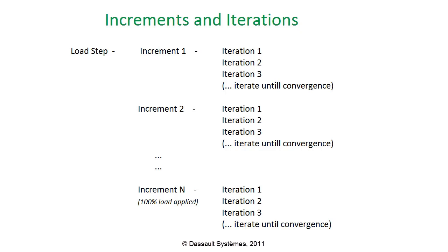It is hard to determine exactly what will be a good initial increment, and Abaqus will in fact let you change even more options, such as limiting the minimum and maximum increment sizes, as well as the total number of increments. However, an initial increment of 10% is generally assumed to be a good starting point, unless you have already run the simulation previously and examined the status file.